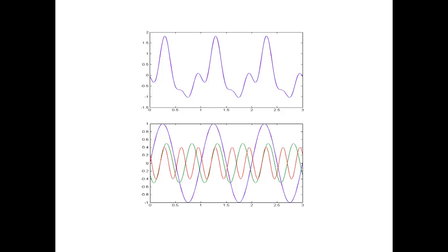Now, knowing that gives you a very simple description of the above signal, as all you have to do is specify what is the frequency of these sinusoids, how much are they shifted, and what is their vertical scaling. That's just 3 numbers per sinusoid. So 9 numbers here will tell you exactly what signal you're dealing with. So this sort of a decomposition is often very useful, and we call this a transform, a different way of looking at your information signal.